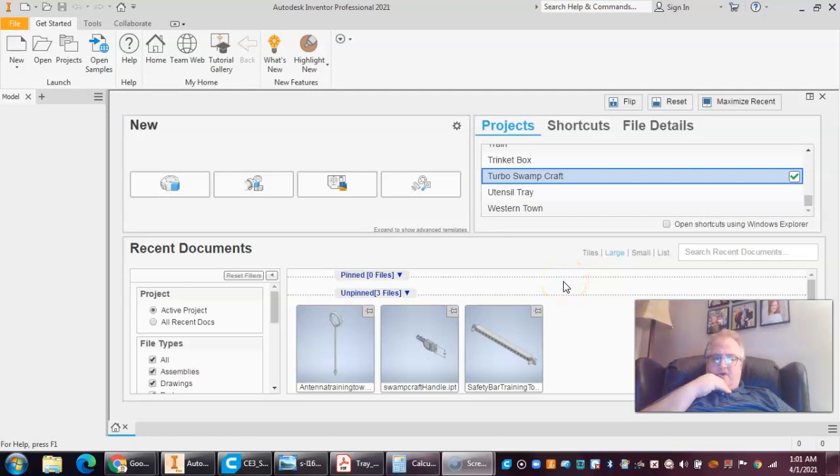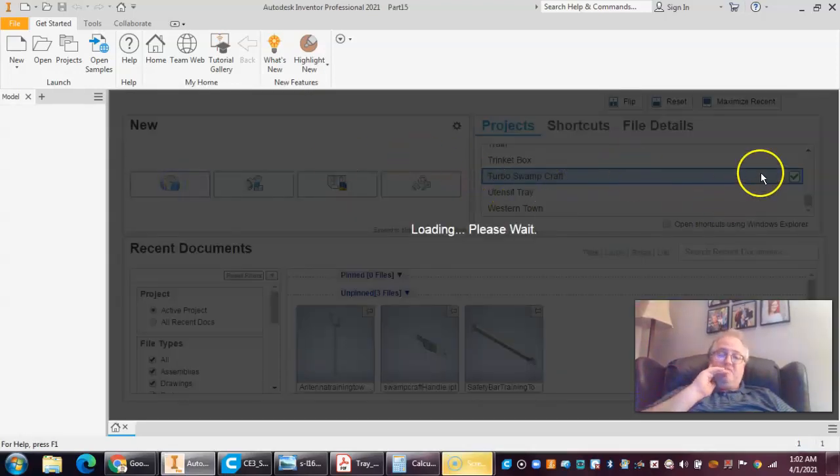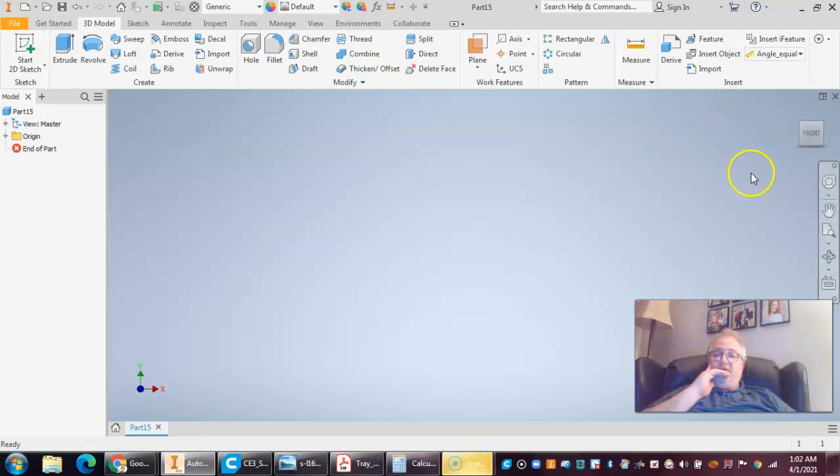All right, so we are going to sit here today, and you guys should have your bridge drawings done in AutoCAD. We're going to use Inventor to do a 3D model of this real quick. So the first thing you're going to do, of course, is to open up Inventor and go to New Part. So we'll get that opened.